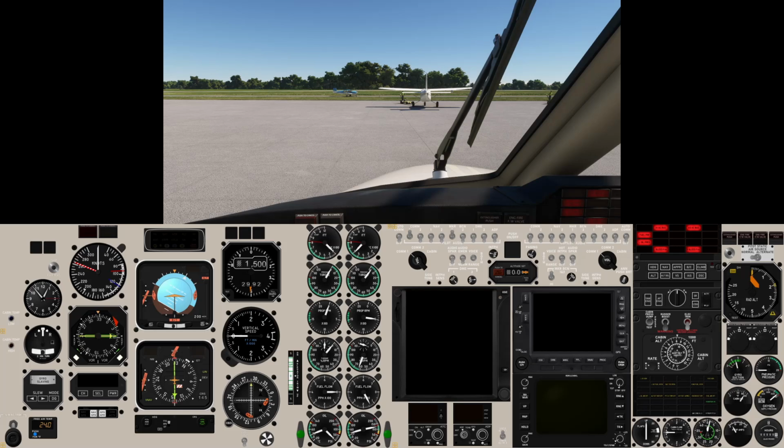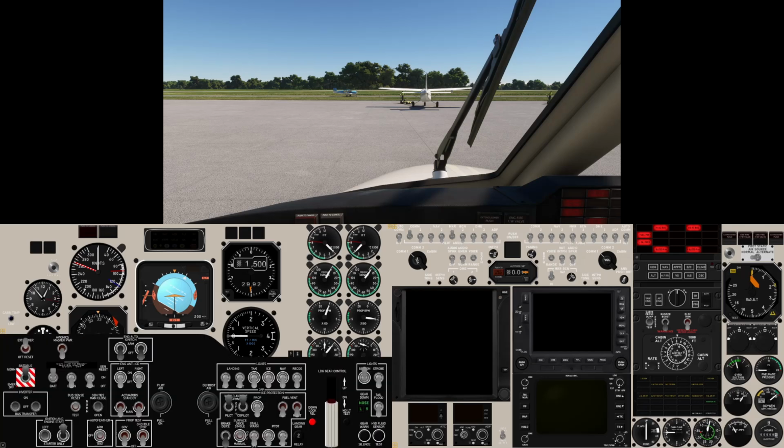Okay, so we'll bring our switch panel back up, then we'll make sure we switch that right generator on. Should have switched that switch off, and we'll go for the left engine. So same procedure. Oh, the only trouble is, I just realised this is a twin, isn't it? See, yeah, we got a hot start there. Do you see that? Hot start on the left engine.